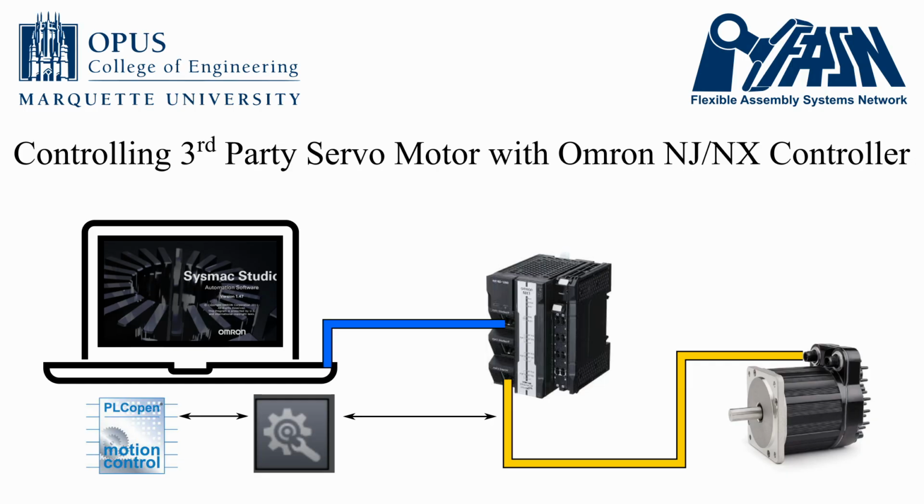This simplifies the integration process, but sometimes there is a need to use a third-party servo drive, and this requires a little more careful attention to the integration. The nice thing about Omron controllers is that they support the EtherCAT communication protocol, which is widely supported by many other servo drive manufacturers. However, just because a servo drive uses EtherCAT, it does not mean it will integrate well with Omron controllers. In addition to supporting EtherCAT, the drive and the controller must have a consistent application layer. Omron controllers use CANopen over EtherCAT.